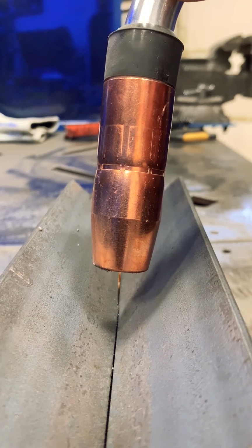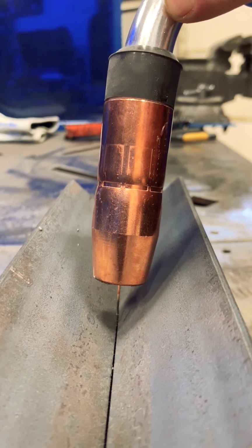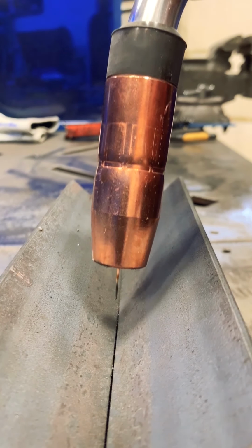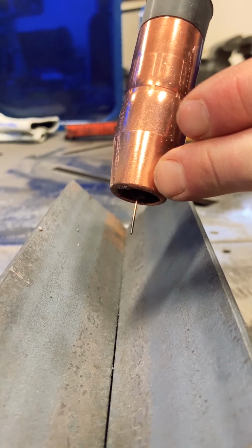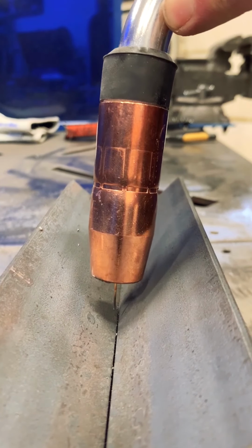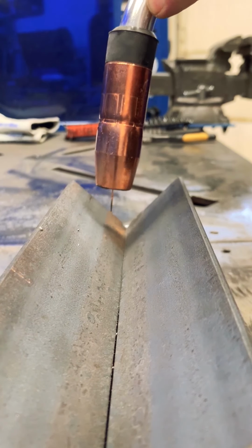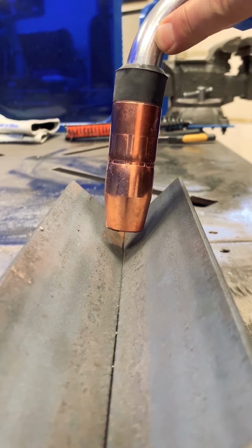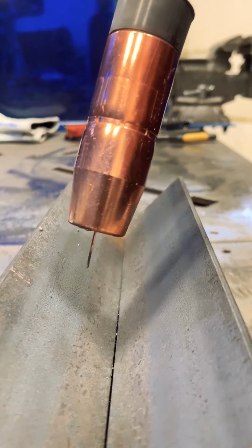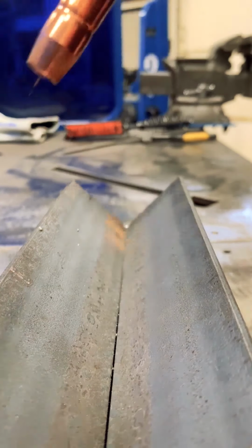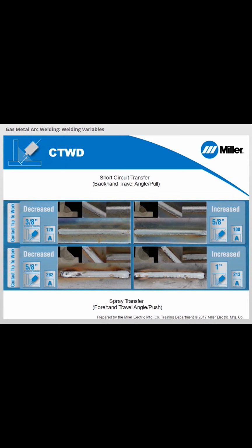Experienced welders are going to be able to understand to use that for root passes and things like that, where they can actually decrease their power, increase their power based on this movement. But really, contact tip to work distance is my ability to control this distance here and maintain it consistently throughout the entire weld without too much variation in my up and down movements, very much so when I'm in constant voltage mode.